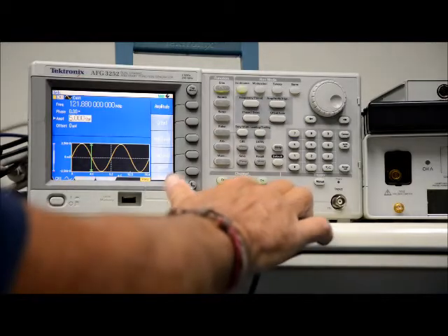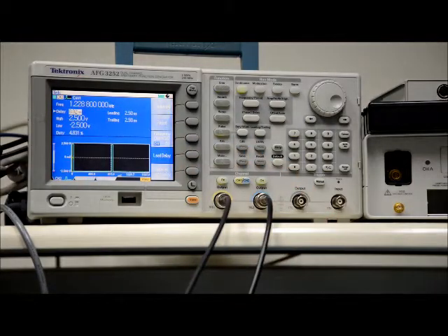For our trigger, we've set it up in correlation so that the trigger will be synchronous with the clock, and we'll use this as our trigger input for this particular test. So the idea is that with each trigger, the two AWGs will be synchronized with the output of whatever output you would like to use for your testing.